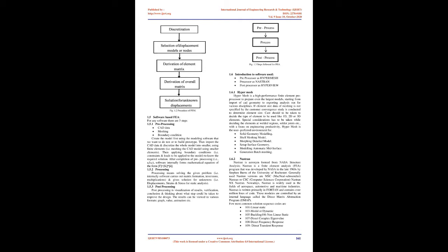Forced vibration: if a system is subjected to an external force, i.e., an external load, then the vibration possessed by the body is known as forced vibration. If the frequency of the external force coincides with any of the natural frequencies of the system, a condition known as resonance occurs, and the system undergoes dangerously large oscillations. When the frequency of vibrations meets the natural frequency of the system or instrument, it causes vigorous damage to the continuum of the system.